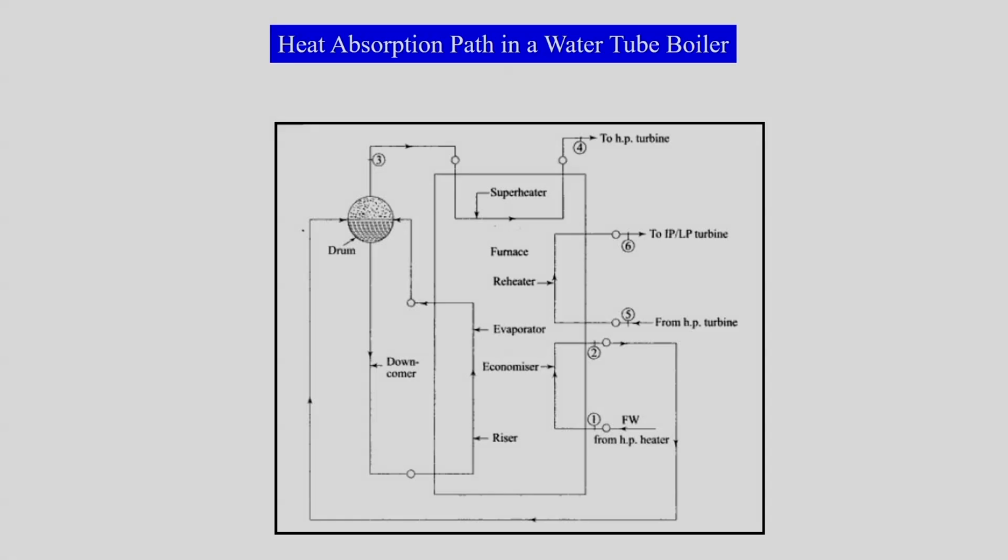where we will have the water, the flue gas which is coming from the top, and then that will heat the superheater, and then it will heat the reheater, and it will heat the economizer at the end, and this is the wall of the boiler. And then in the wall of boiler we have the riser tubes, and these riser tubes will rise the water. This is downcomer. So this is the drum which we are having outside the boiler shell. This is one of the schematics of the boiler or steam generator.